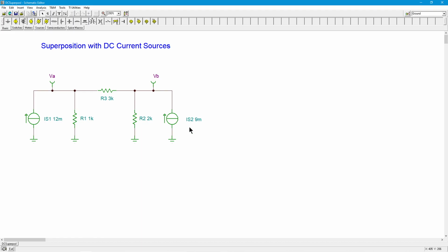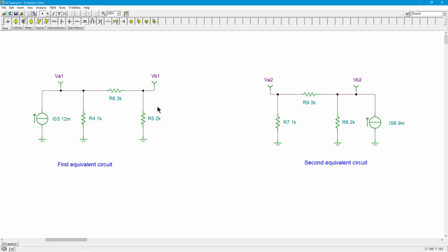In the case of a current source, it's the exact opposite, right? It's an open because any resistance in parallel with it would be limiting the voltage it could produce. So the ideal case, right, would be an unlimited case. So the paralleled resistance for a current source, the ideal internal resistance would be infinity. So you open this, right? Don't short it, open it, right? So that's, like I said, we had the source here and we had a source here. So we just open them, we pull them out.